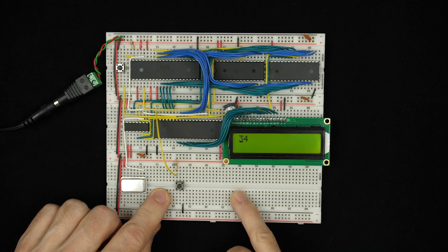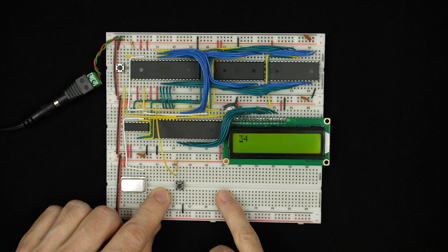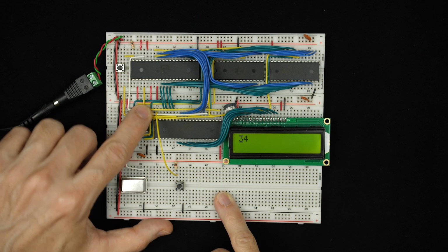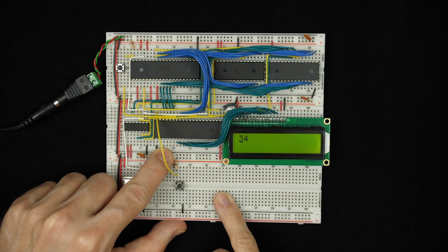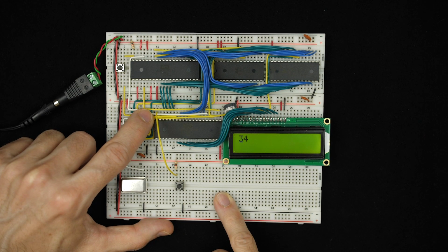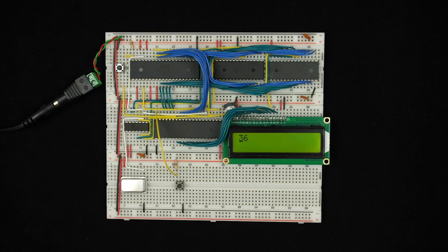If you're doing this project at home, you might want to try adding several buttons, and not just hooking them up through the CA1 bit, but also hooking them individually up to individual inputs here. And then you could perhaps diode OR them together so they all trigger the interrupt. But anyway, hopefully this gives you some ideas of where to go from here.